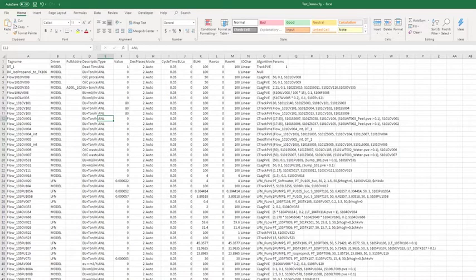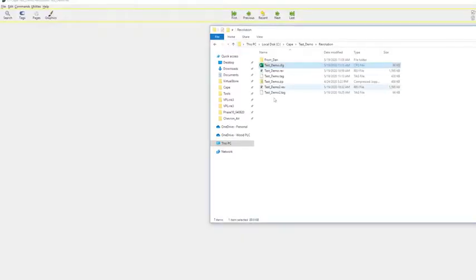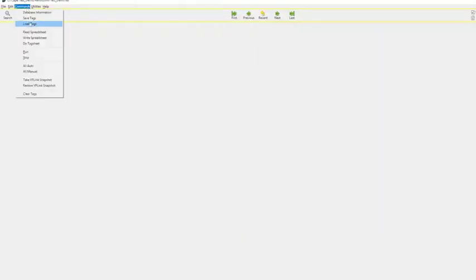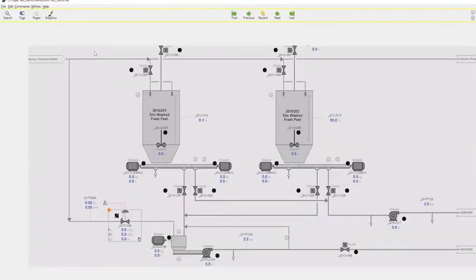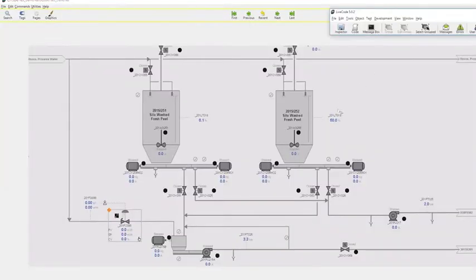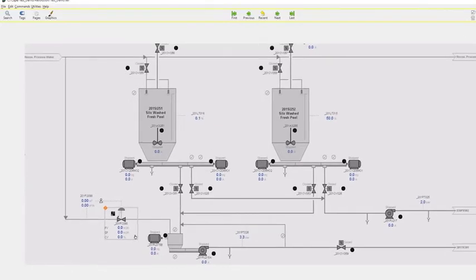Once we are satisfied with review of the tags, we can then import them to the VP-Link server. VP-Link uses LiveCode as the graphical user interface or GUI and imports the tags. This step involves the process of importing in an HMI screenshot. The user can then add the tags on the HMI screen and then populate the image with a representation of the process graphics.